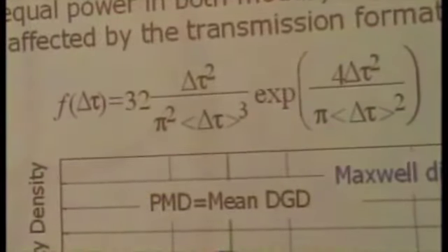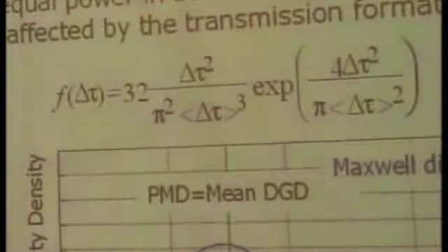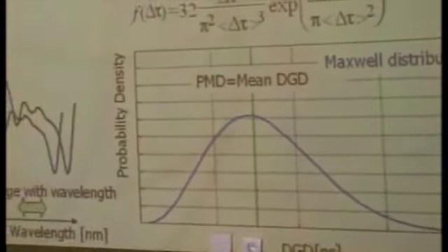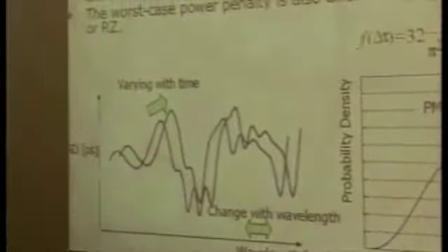So this means the polarization state in a fiber often changes with time or situation. And so the maximum link DGD is set to allow no more than a given power penalty in the worst case power splitting ratio. This means the worst case is such a case that the signal power is split equally to the two polarization states.